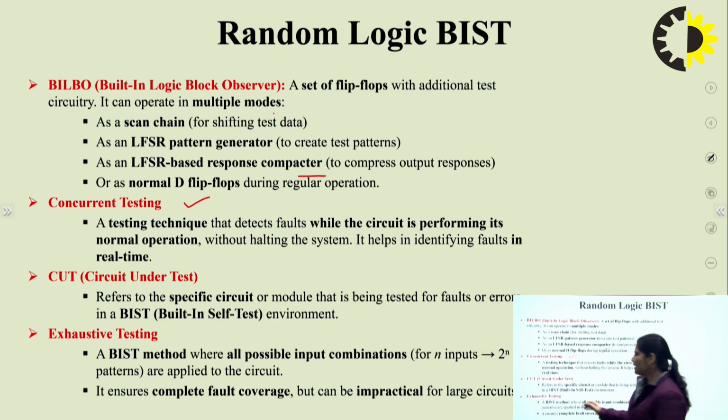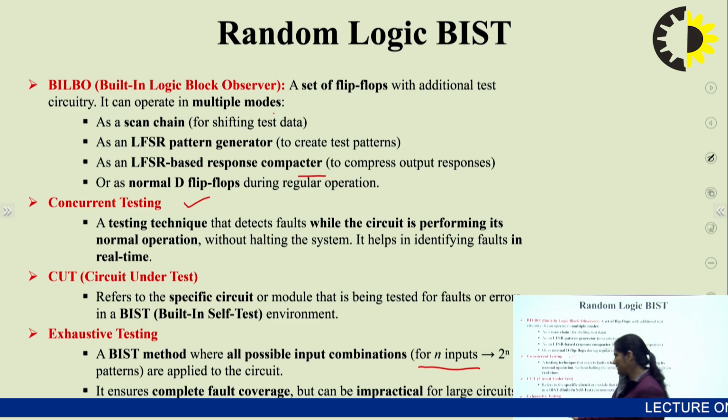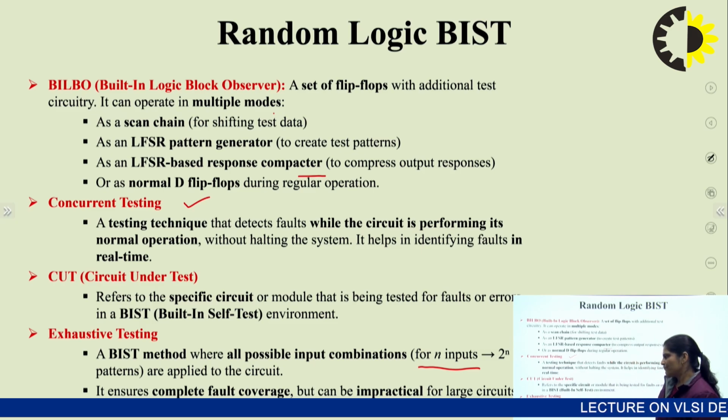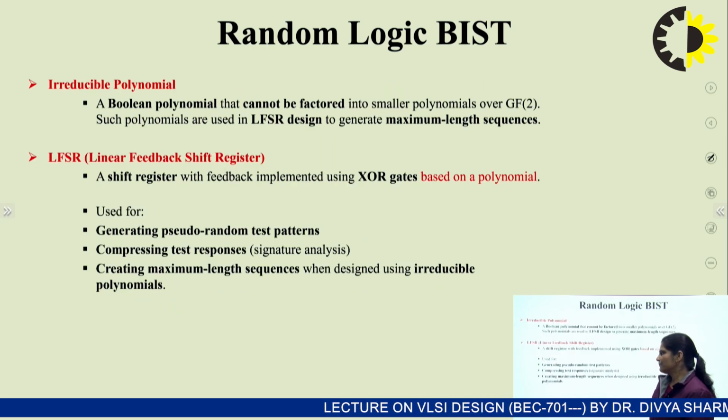Now, next is exhaustive testing, a built-in self-test method where all the possible input combinations for n inputs, that is 2 to the power n patterns, are applied to the circuit. It also ensures complete fault coverage, but it is impractical for large circuitry.